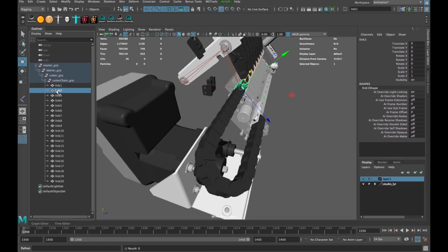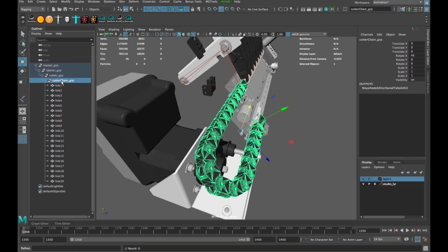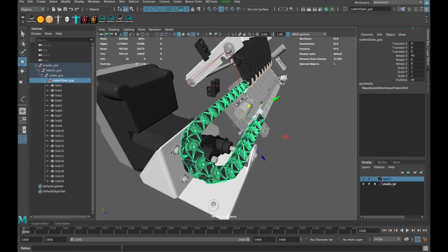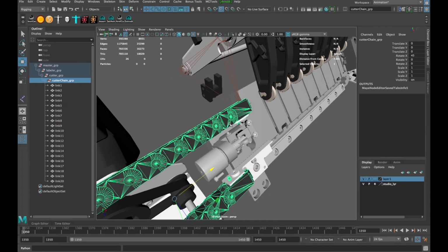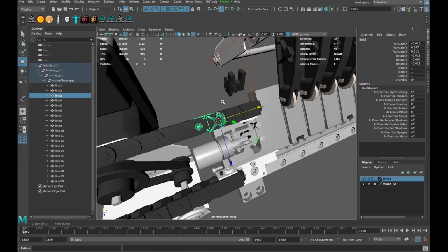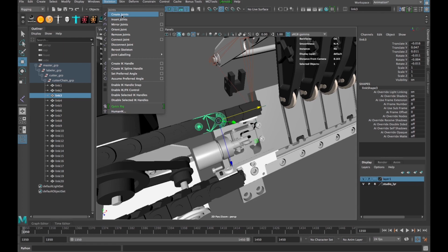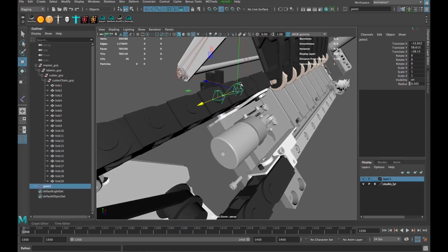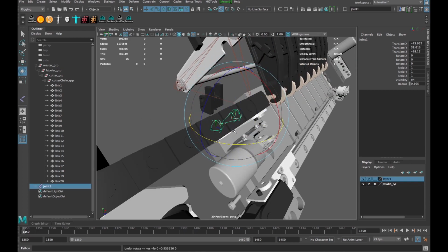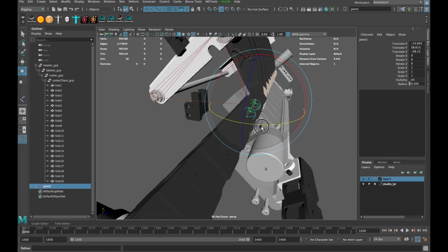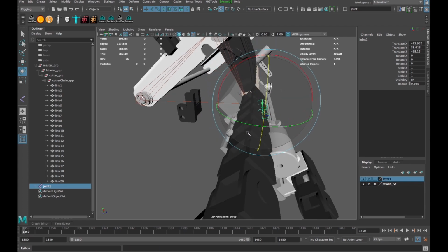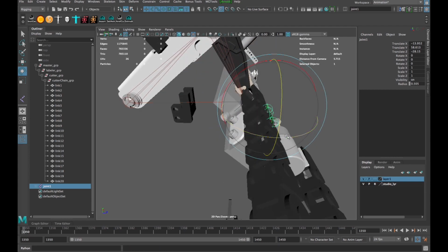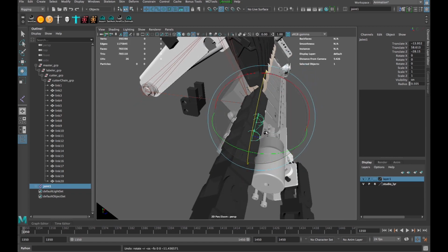Each of these links is a separate object, and then they're inside of a group that's rotated. Now, if I were to start creating my rigging to drive each of these links, I should say, create joints to drive the links, when I create a joint here, it's going to be oriented up and down. And so if I rotate the joint, there's no axis that's aligned to the way that this chain is oriented. It's just bad rigging technique.